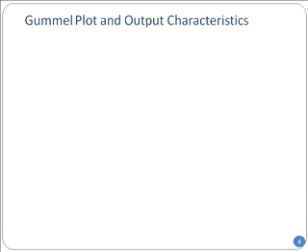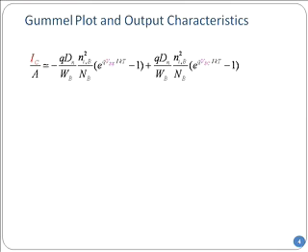Now one plot that is very important, and that essentially captures the essence of what a good bipolar junction transistor is, is given by this following ratio. But before I get there, first of all notice that the collector current depends on the base emitter voltage, right? Because I'm forward biasing it, that's how the electrons are getting over the barrier. And also on the base collector bias, because that is on the other side, the reverse bias is pulling the electrons out into the collector.